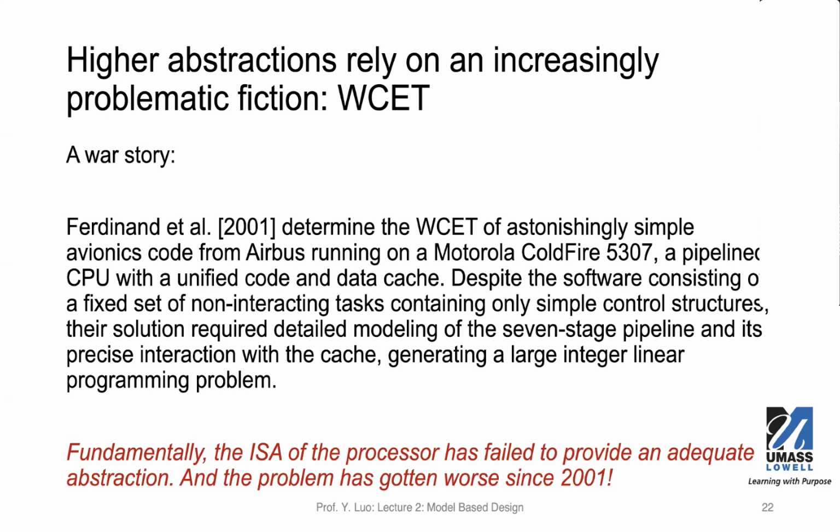Pipeline means that when you have an instruction, you execute the instruction in terms of stages. The simplest pipeline could be instruction fetch, instruction execution, instruction commit. So the actual processor will have more stages than the example I gave here. But the concept of this pipeline is to basically take advantage of the resources on the chip so that you can have more than one instruction executing at the same time at different stages. This will greatly improve the CPU performance.